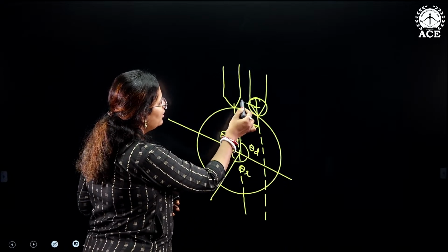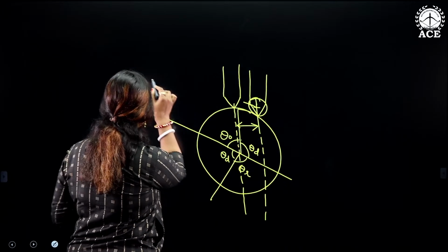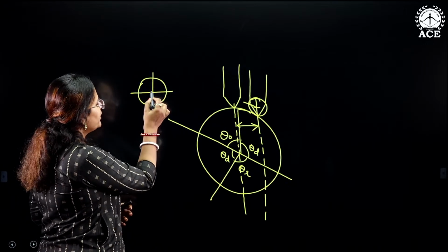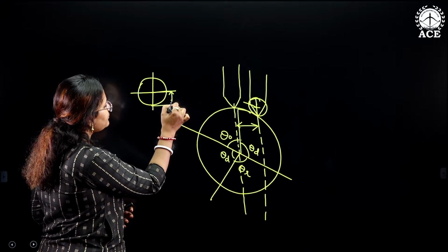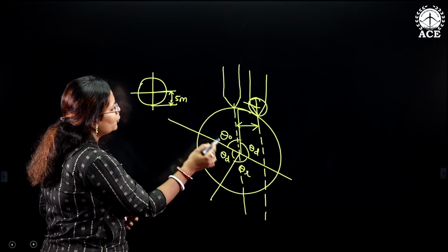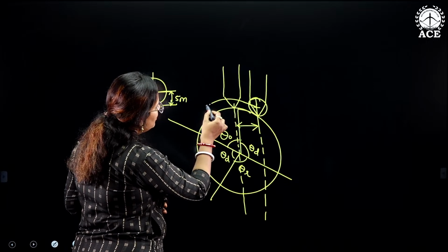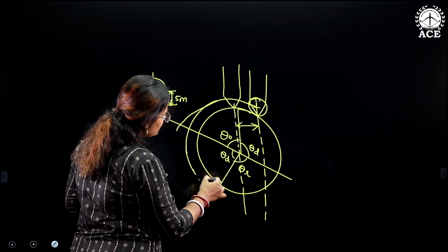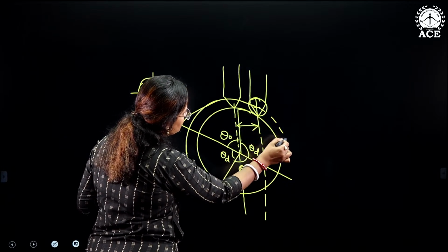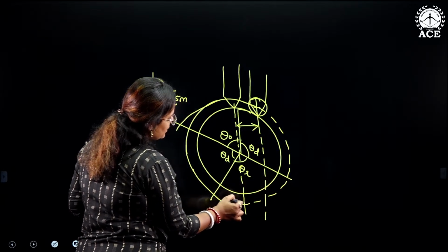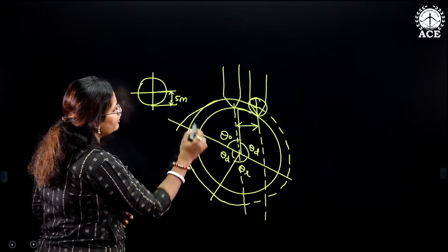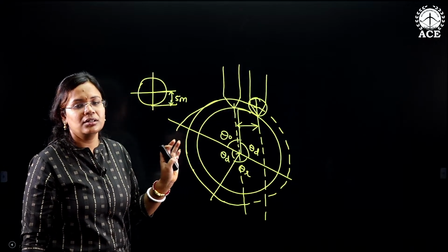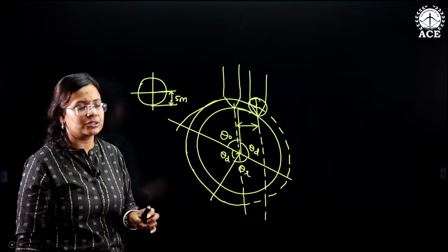Let us say the diameter of the roller is given to be 10 mm. So the radius will be 5 mm. You also draw a prime circle parallel to the least radius circle, in a dotted line. The radius of this particular circle will be the summation of the least radius and the roller follower radius.